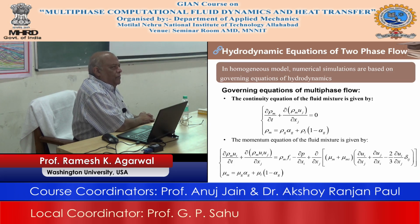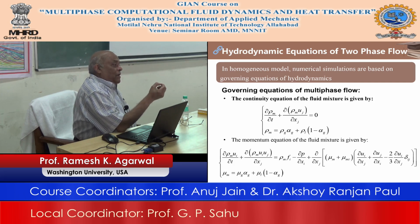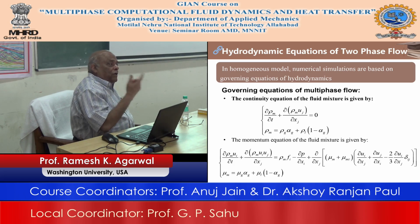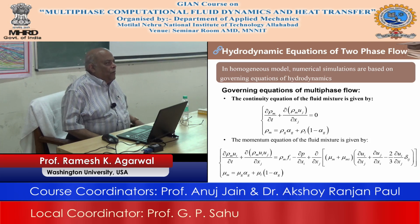Yeah. That's correct. The thing is that at t equal to 0, when you start the iterative process, that is the time you are able to identify by the calculation of the flow field where the air is going to be, in which grid cell the pressure is less than PV. So it is going to be a solution in the iterative process, unlike what we discussed before.